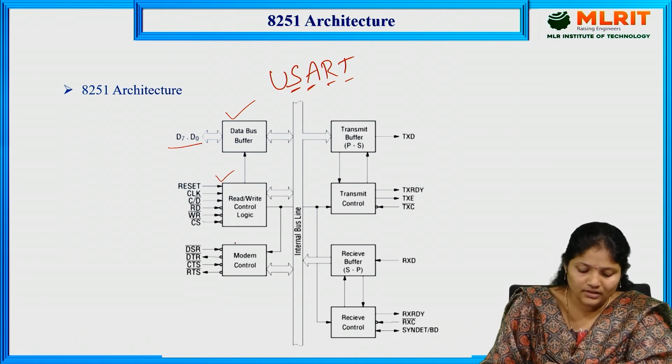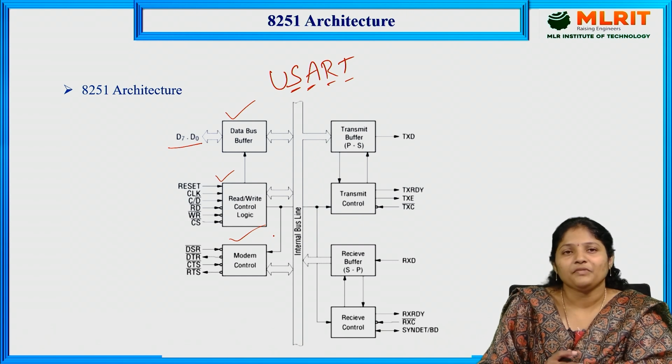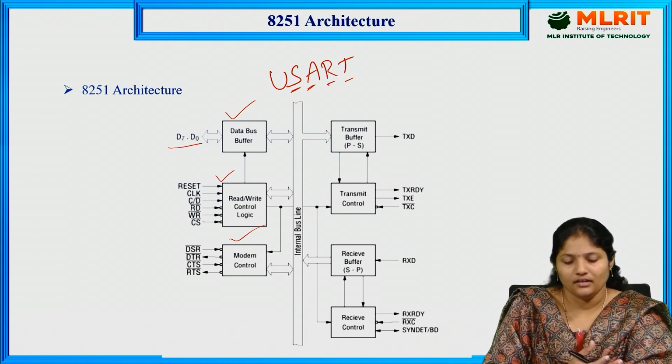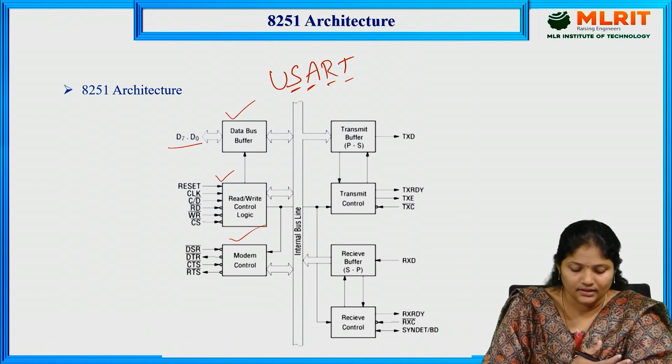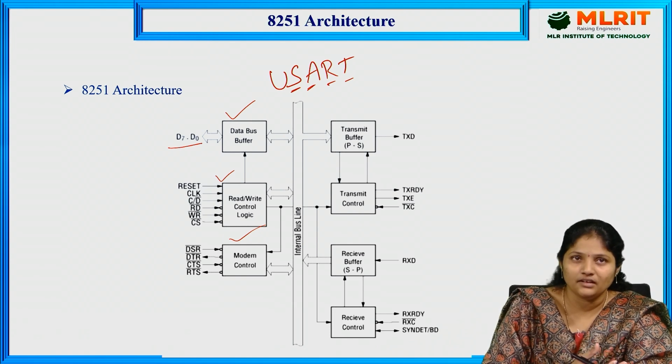Coming to the modem control, this modem control will be used to synchronize with the 8086 for handshaking or synchronization to transmit or receive the data, whether the transmitter is ready, whether the data set is ready, or the command is ready.